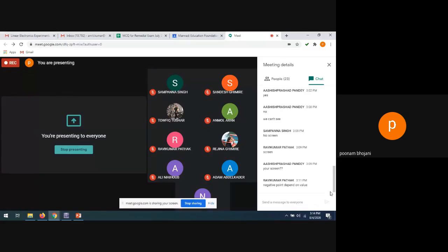You have to make very small changes in the RC value, and then check whether with this small change we are getting the proper smoothness or not. And then again change it by adding and subtracting. You can get the value, get the smoothened waveform. But you have to check it for everything. I can't directly change 1K to 100, right? You cannot make such big changes. You have to make small changes and check.